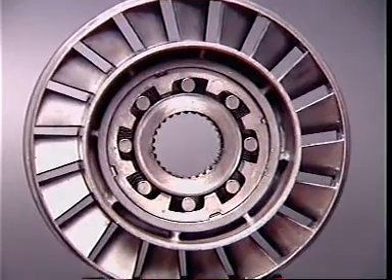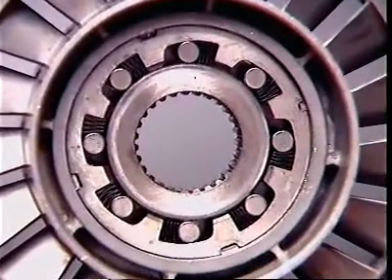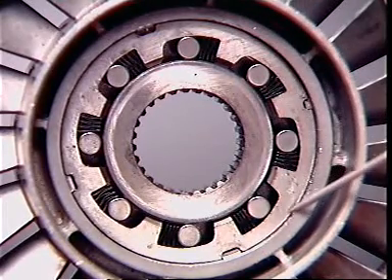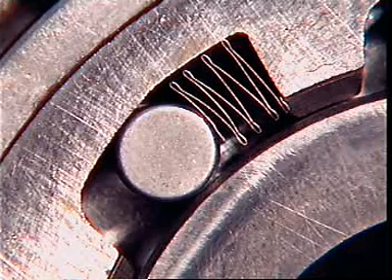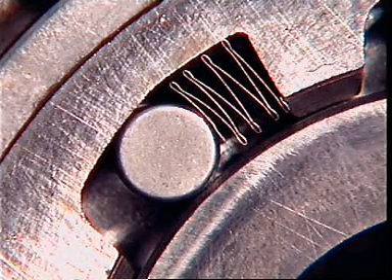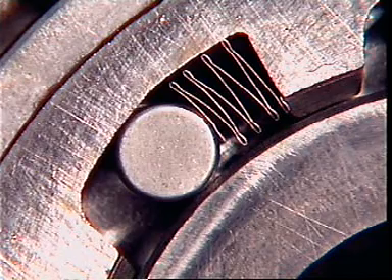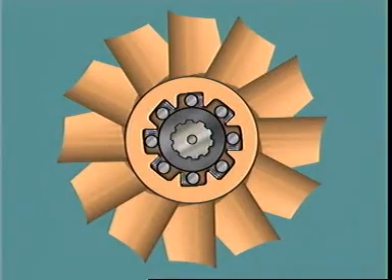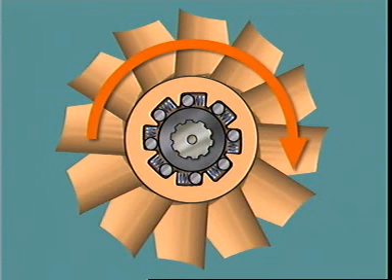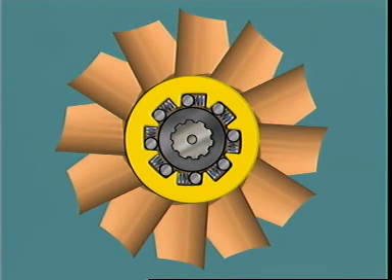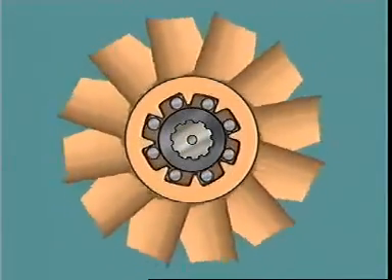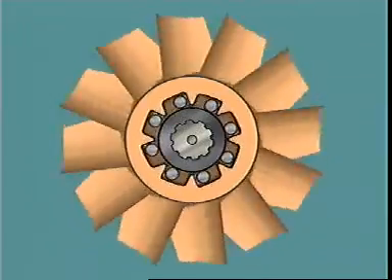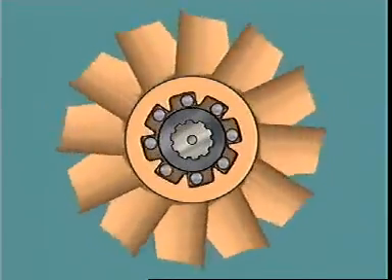In the roller-type one-way clutch, the inner race is splined to the stator support. The outer race has wedge-shaped segments, which retain the rollers. In each segment, a waved compression spring pushes each roller towards the narrow end of the wedge. A force on the stator blades against engine rotation locks the outer race onto the rollers, wedged between the two races. Turning the stator with the engine rotation eases the wedging, and the stator rotates with the impeller and turbine.